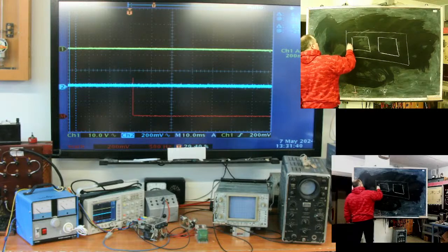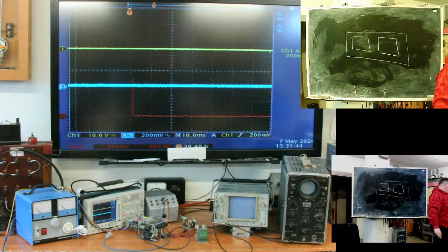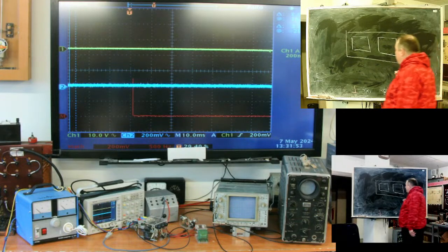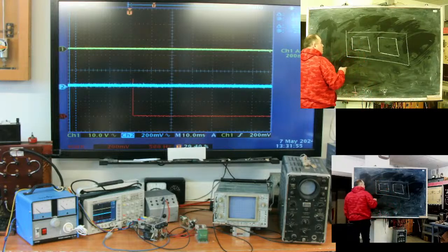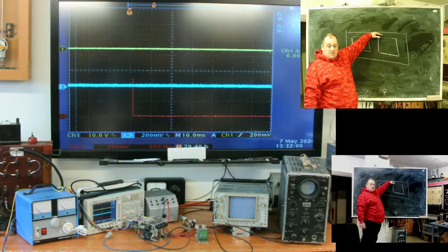What kind of moment? In case of a three separate transformer, the 150 Hz component can easily circulate in their cores. Nothing on its way. Here, in this part, the sum at 50 Hz will be 0. Yeah? Sum of flux.